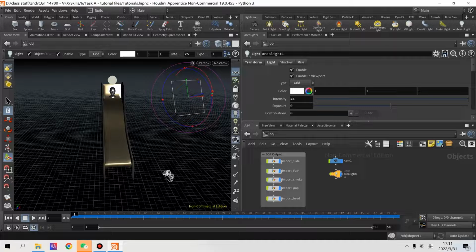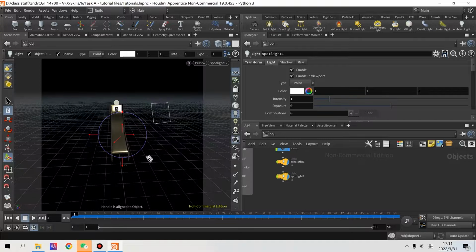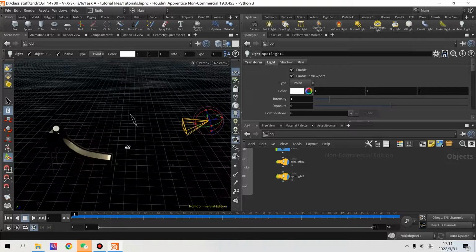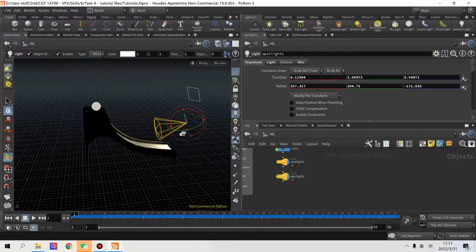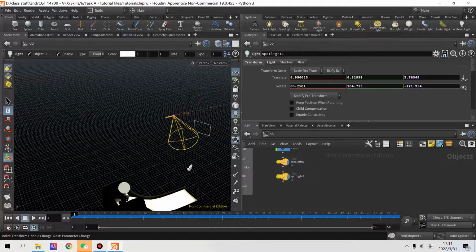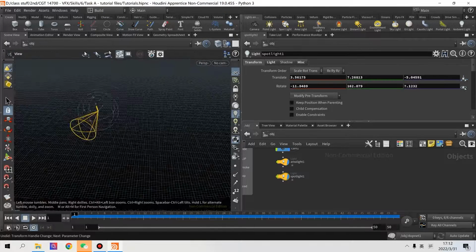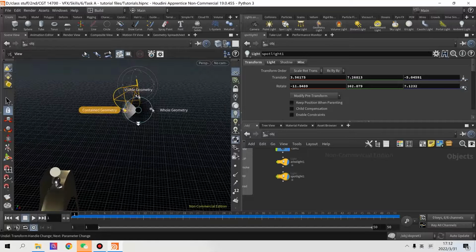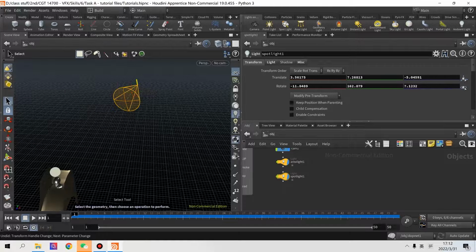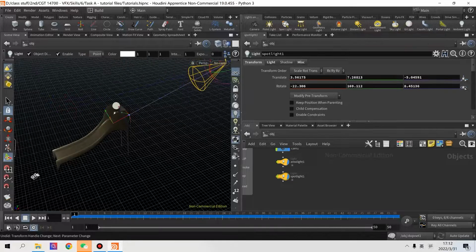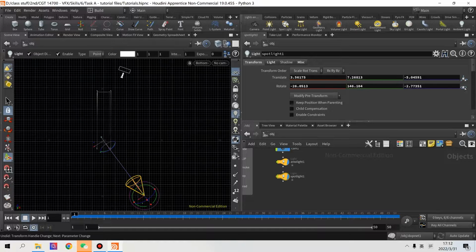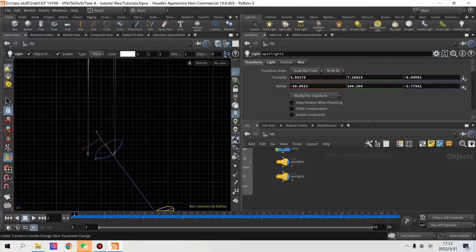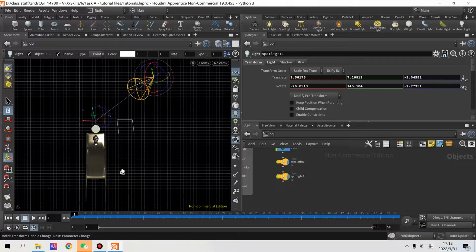And we're gonna add another light that shines on the back side of the slide, which is the spotlight. And we're just gonna put it in the correct place with rotations and translations. I'm just gonna put the light to the back in order to give some light source to the head and all of the fluid back there. And we can actually adjust the point where the light is gonna go. So that's pretty convenient. And if we're gonna put it in the precise place, we can always choose different perspectives, like front view and back view, top view, to adjust its place.